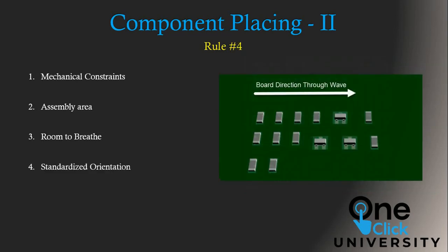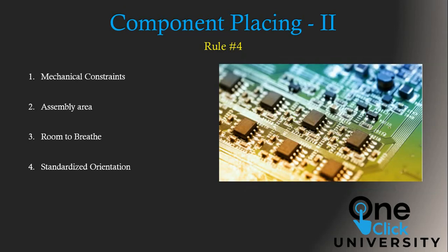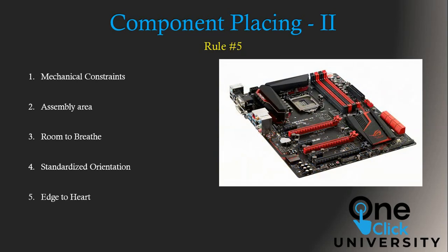Number 4. Keep similar components facing in the same direction. Best example I can give here is of the living room. Everyone would want their chairs or couches facing the television, won't they? Similarly, place the components with the same orientation, or say keep all the similar ICs having their notch or the first pin of the IC facing in the same direction. This reduces the confusion about the placing of the ICs and avoids damage to the components as well as to the board.